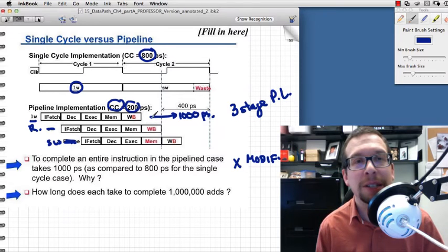The difference in the end is that for 3 of these instructions to occur, you have first a fetch of the load word, then you start decoding the load word instruction. As soon as the decoding starts happening, you can fetch the R type instruction. Once the execution starts on the load word, the decoding on the R type can start, and you can fetch the store word.